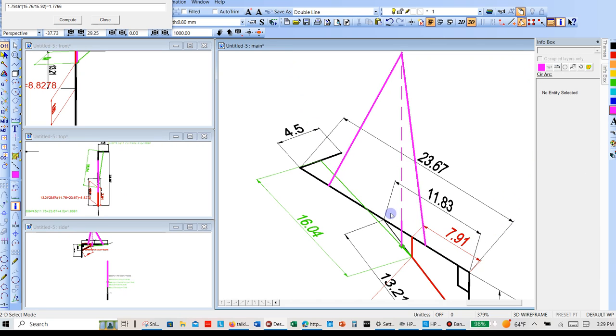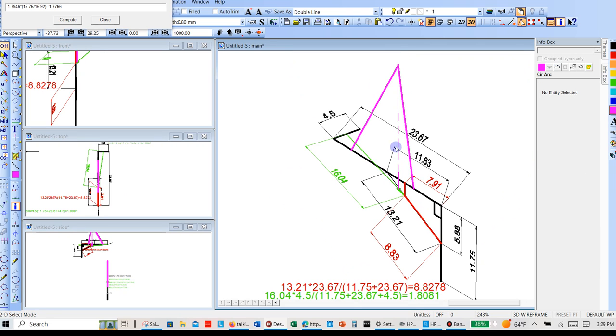That's how you would do it. You would swing it till it matched, and it would actually still lift it here. You'd be picking up a lot more load on that sling, but that's how you match it up, right? And then these two slings can actually not be customized, right? And then with the 3 inches off center, you could just use a small chain fall to go from here to here, enter, right? And that would be pretty much it.